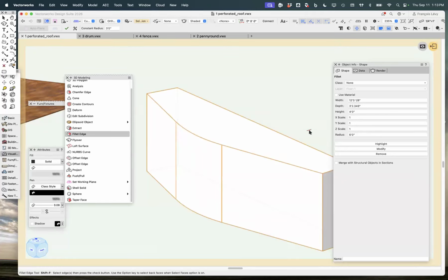Now, conceivably, you could have made a 2D polyline construction with that curve in it and extruded that, and then shelled that. Yes. Yeah, right. As is the case in Vectorworks, there's like 12 different ways to do something. No, in fact, I like the fillet more.